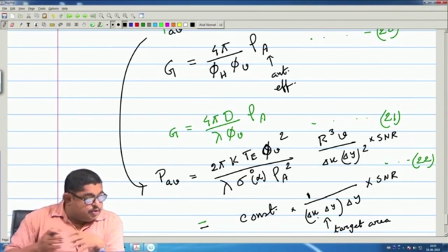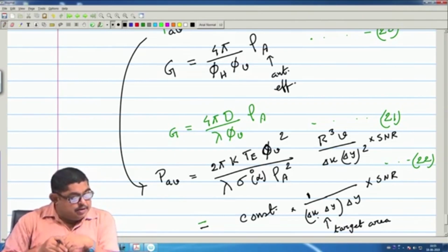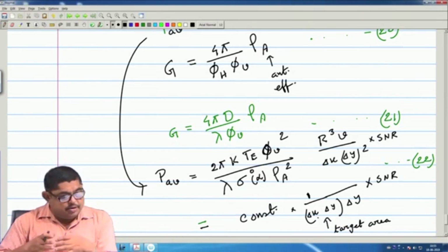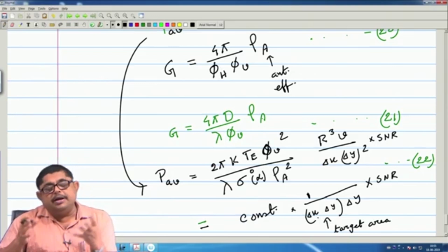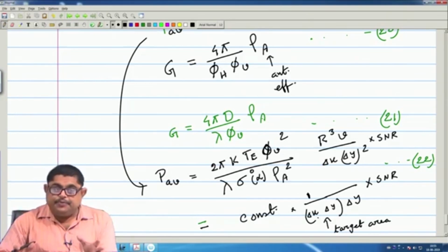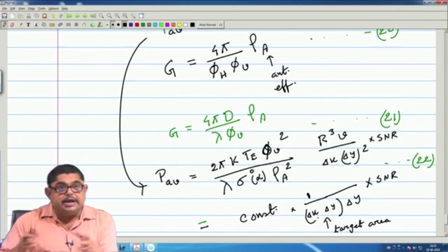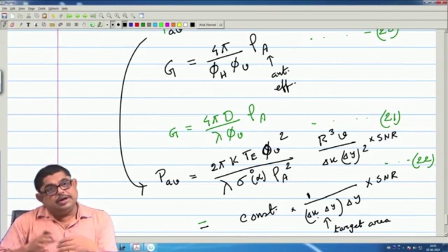So, cross range resolution even after SAR processing is dependent on the radar receiver's detectable SNR. Also, it suggests that one cannot go on reducing antenna size to improve cross range resolution.